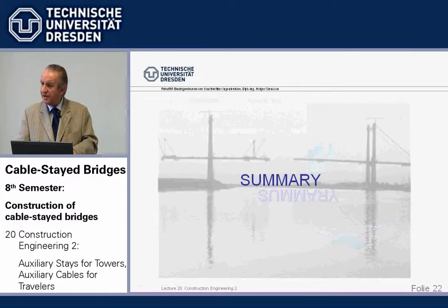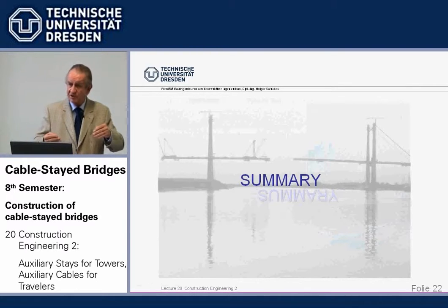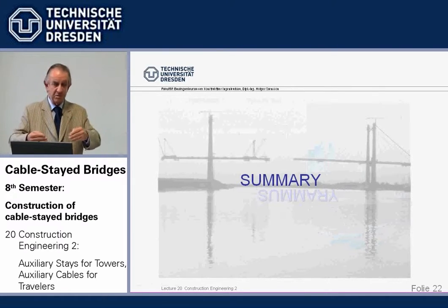At the final stage, after shrinkage and creep, we cannot do these calculations by hand, because here it has to be precise, and we have a highly statically indeterminate system. So we use a computer, and I've shown you what commands you have to give the computer to apply loads, to open joints, to be able to take out elements, and in this way to dismantle the bridge.